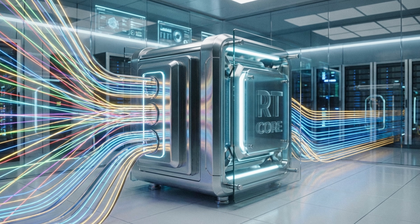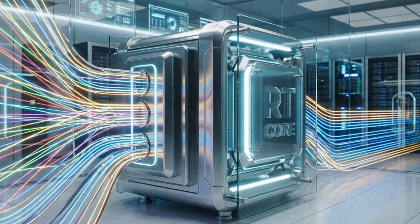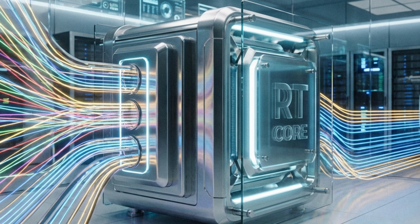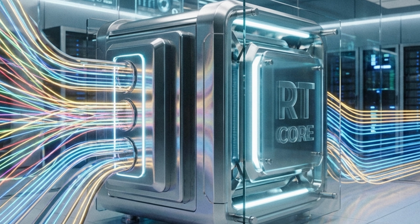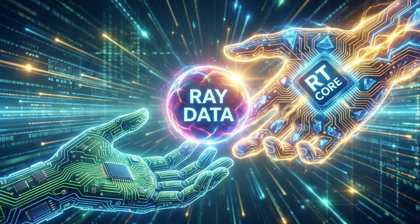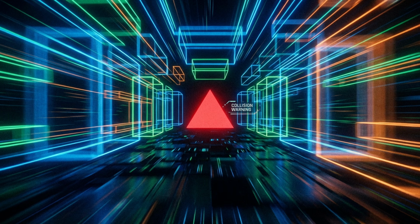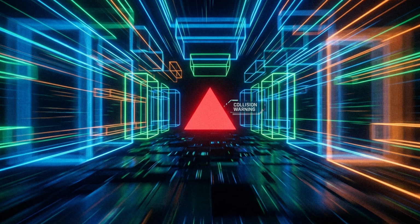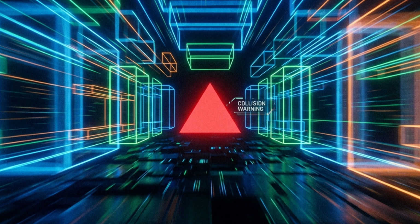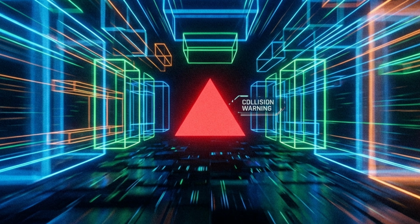To solve this specific bottleneck, the ray tracing core acts as a dedicated, specialized coprocessor designed exclusively to accelerate the traversal of this bounding box tree and perform the final ray triangle intersection tests in hardwired silicon. When a program casts a ray using modern application programming interfaces, the hardware immediately hands the mathematical traversal of the tree over to the ray tracing core. The core evaluates the bounding box intersections, rapidly navigates the tree hierarchy, and performs the precise mathematical intersection test against the geometric triangle, subsequently returning the exact hit data to the standard processing cores.